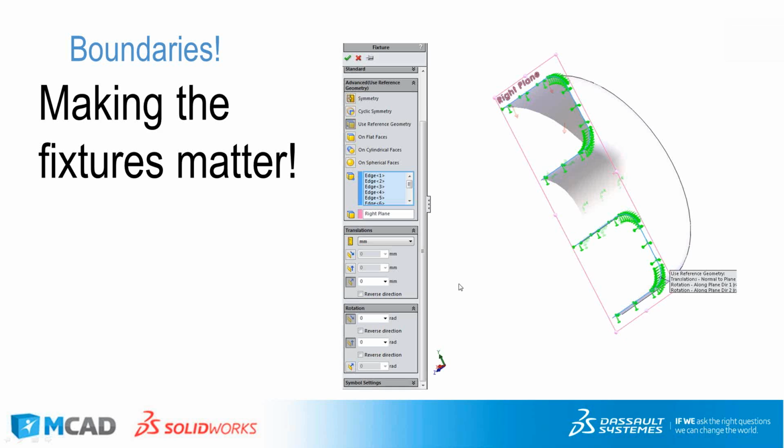And instead of just using a symmetry or something like that, I've bound it against the right plane, told it it couldn't move away from it, just like if the other half of the shell was there. And I've told it it can't rotate about the first two planar directions, but it can rotate around the interior or normal plane direction because of the deformations that will be happening. So in this one, you can see how I was able to make this boundary condition without